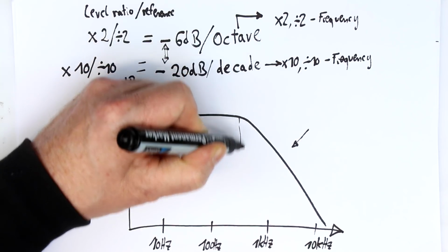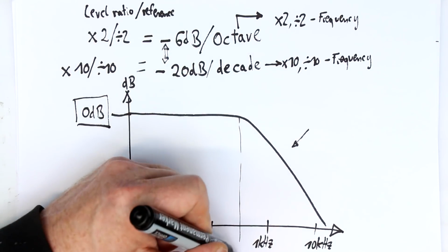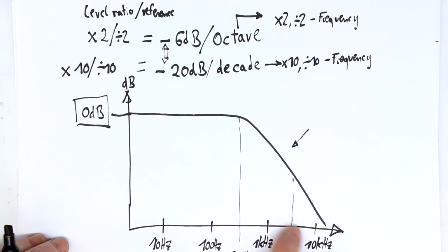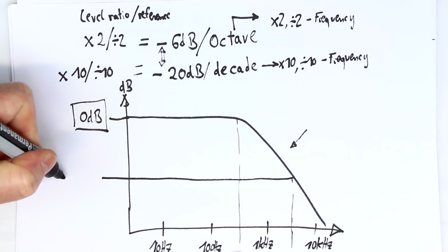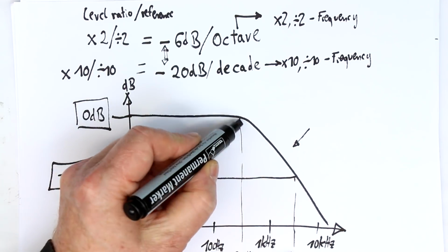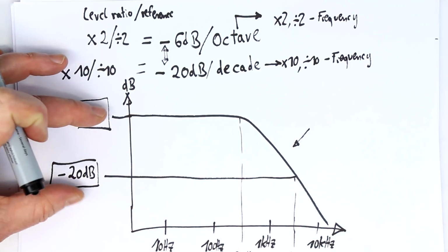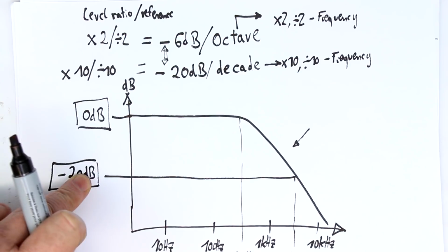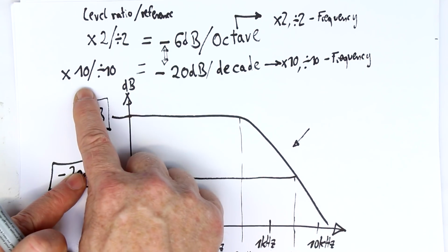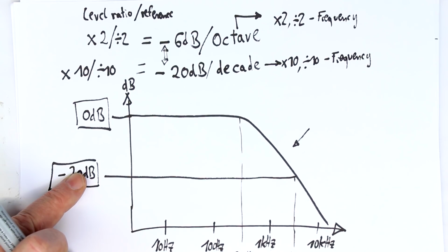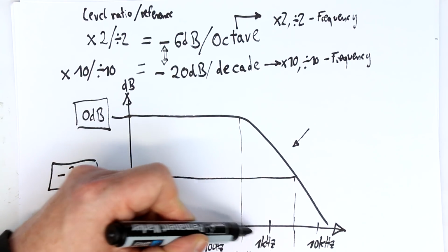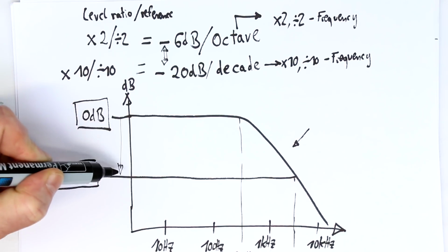And now let's see here where the roll-off starts, we have, let's say, 300 Hertz. And here we would have 3 kilohertz. So that is 1 decade difference. And here, for example, we could find minus 20 dB. So in one frequency decade from 300 Hz to 3 kHz, we have 20 dB level fall off, and that is a filter that is linearly falling off, a low-pass filter with a linear fall off, because for the same amount of frequency increase as a factor, we have the same factor as drop in level. Factor of 10 frequency increase, factor of 10 going down in level.